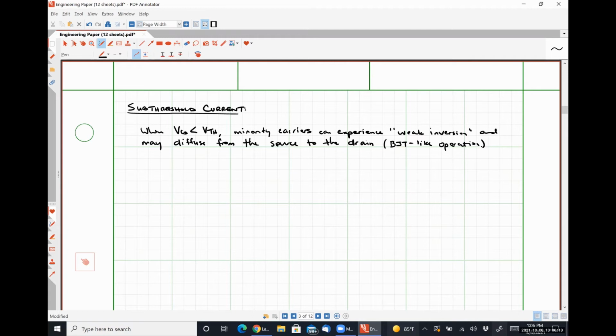And the level of doping concentrations, as well as the physical size of those regions, are vastly different between those three areas, right? So our emitter, where our charge carriers come from, typically has extremely high concentrations. And our collector, where our charge carriers go to, has much, much lower concentrations than the emitter. And our base is kind of somewhere in between.